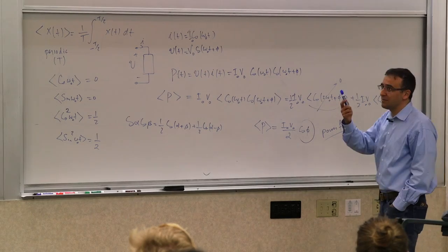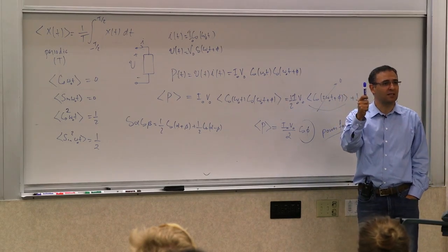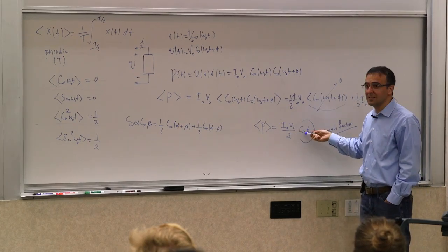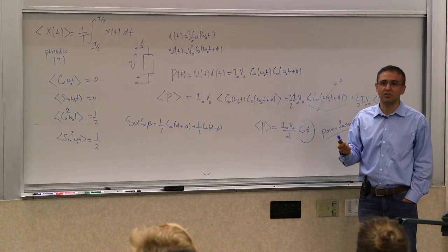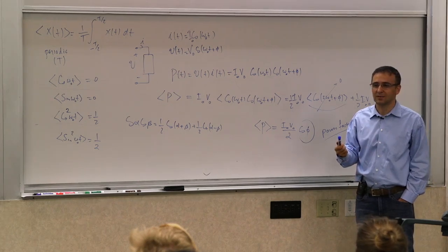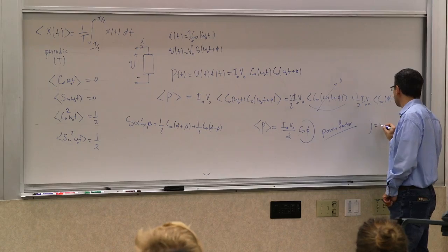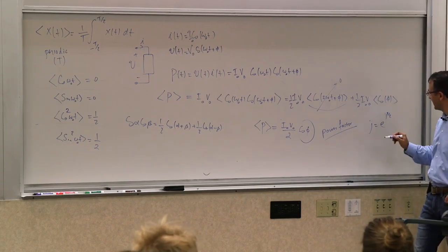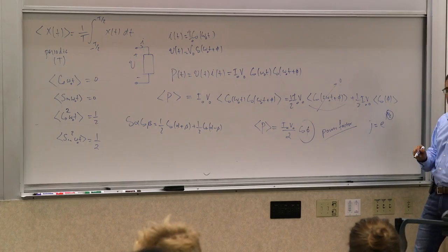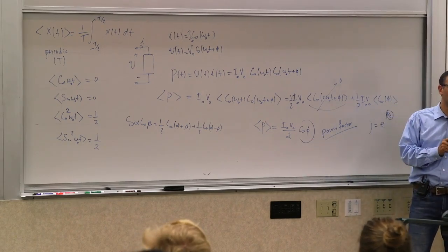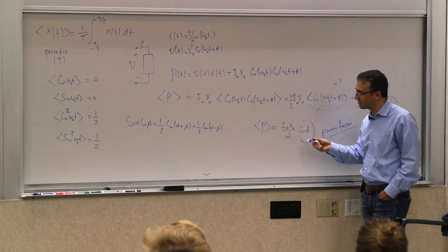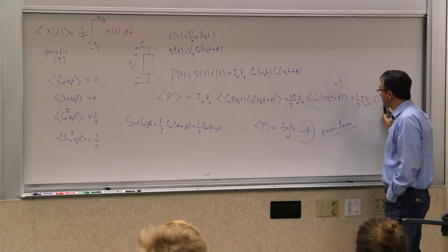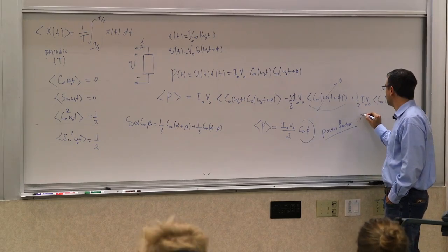How do we see that? Because if you remember that j in the impedance, right? The impedance of an inductor is j omega L. j means phi is what? What is e to the j? I'm saying, what is j as e to the something? It is e to the j pi over 2, right? What is this phase shift? 90 degrees, pi over 2. What's cosine of pi over 2? 0. So that's how it's captured here. Right? Make sense? So this is the power factor, sometimes shown as PF.